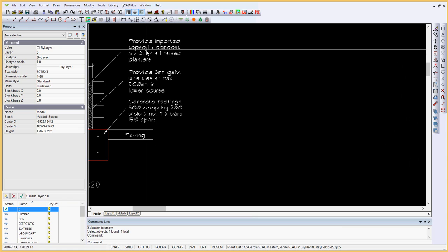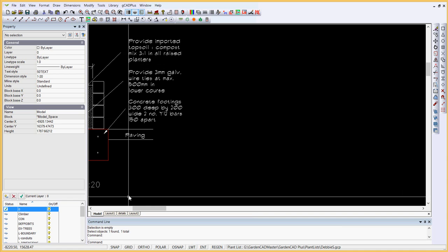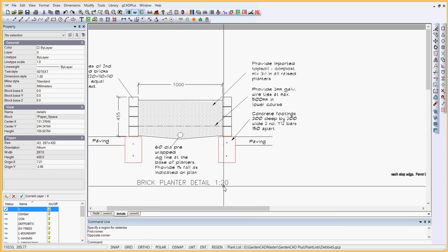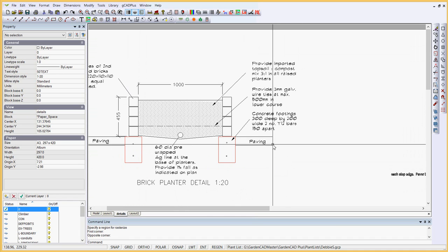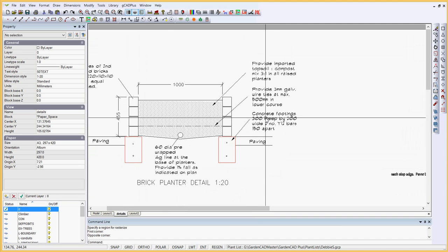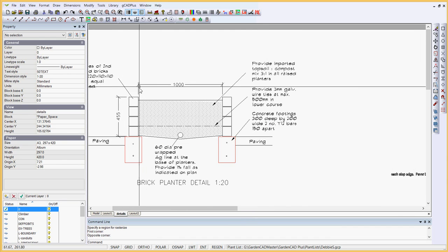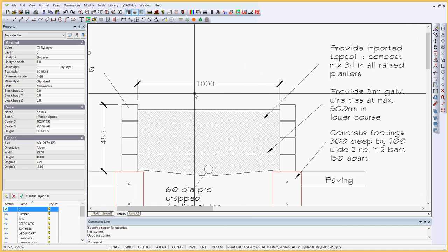I think I'd be inclined to use uppercase for that, because a construction team will have to work from this, and quite often when you're out in the field, uppercase is a lot easier to read than lowercase. So the text is in a particular style. I'd go back and change that to uppercase, and our dimension style with its architectural tick marks and so on gives me the sort of distinction between notes and dimensions.